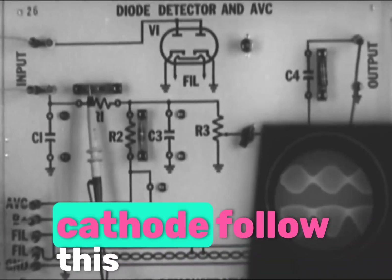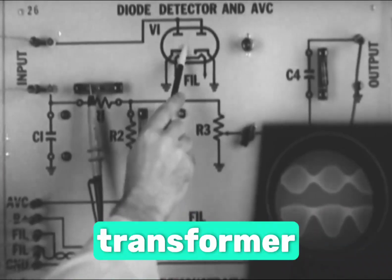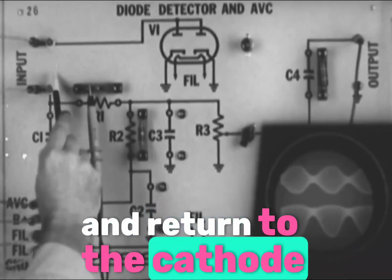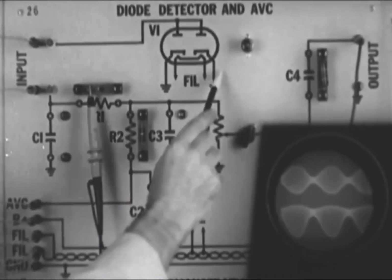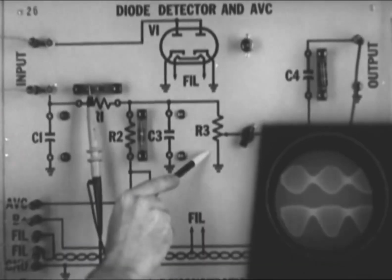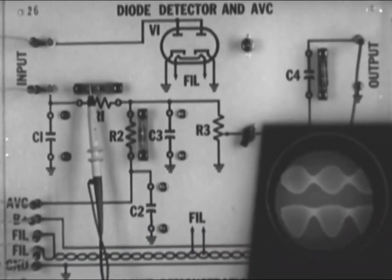Electrons leaving the cathode follow this path through the input transformer and return to the cathode through R3, always going from top to bottom or from negative to positive. Since this end of R3 is grounded, the other end must be negative with respect to ground.